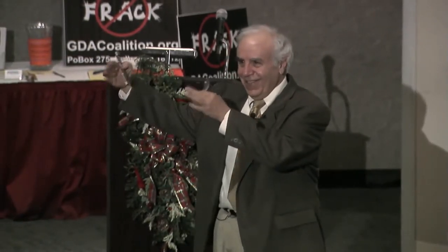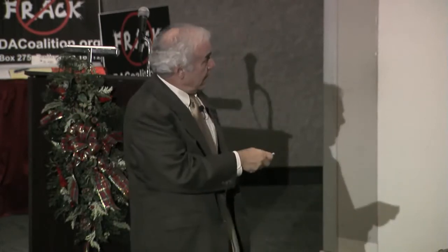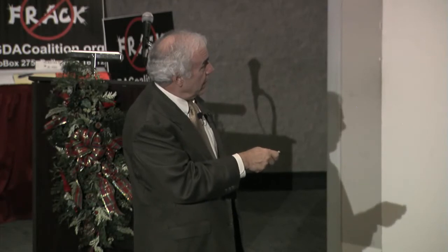Or the doghouse is the place on the drilling rig where the guy is controlling this process, and he's got an LCD panel screen, and this is what he sees. It doesn't look like a cartoon, and he's getting constant signals from the electronic device down here that goes through the rock and tells him exactly where that is to within a few inches. And then he can control the speed and the angle that motor has.